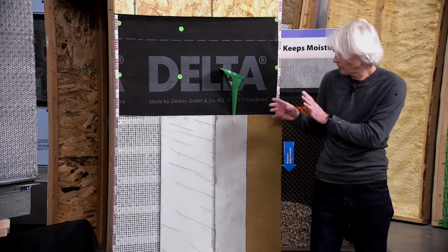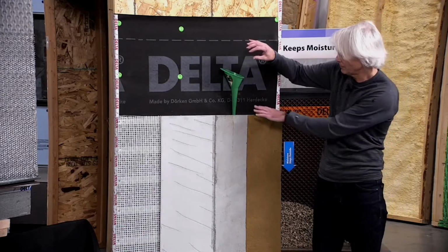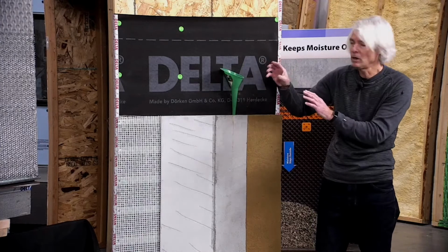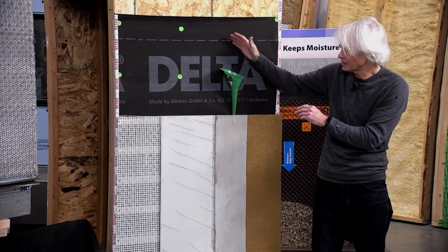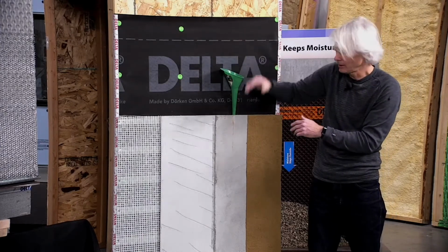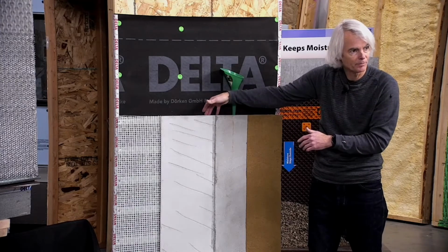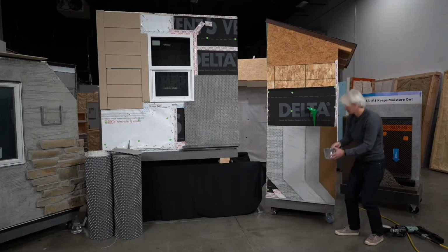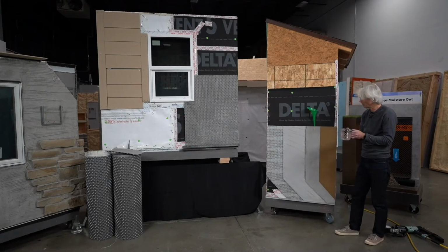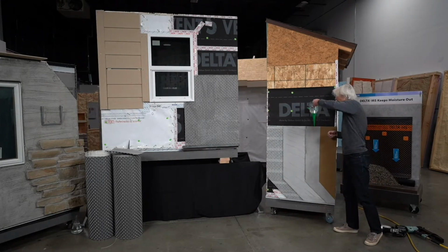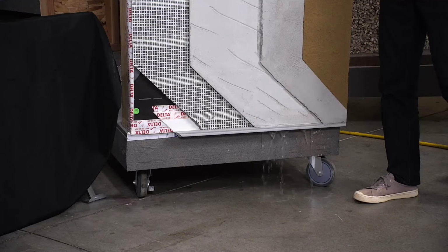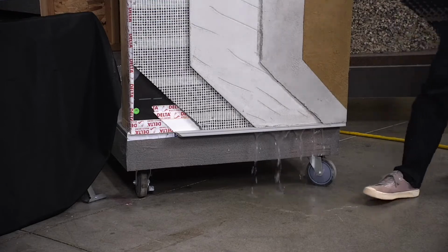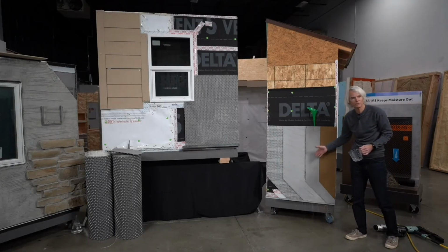So what we really want to focus on at this point, we're over this Delta Vent S product, is I want to show how quickly water can actually drain between the weather barrier and the backside or the gap that's been created of this particular stucco product. So I'm just going to reach down and we're going to grab ourselves a solid pint of water, and we've put this funnel in there between, and so I'm going to dump this right into the wall, and you can see the water's already gushing out of the bottom of that wall. That is some serious, when we talk about drainage, that's some serious water release.